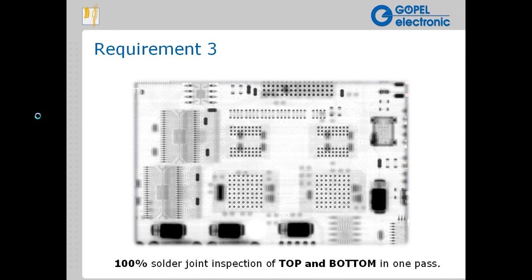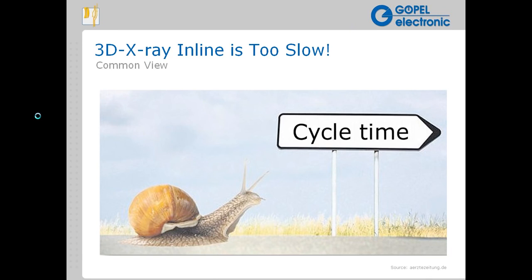To give you an example of why we are fast with X-ray, conventional AXI systems typically use a stop-and-go stepping methodology. Anytime you use a stop-and-go stepping technique like this, you have settling times that are required between images to allow mechanical aspects of the system to settle. Once you move those mechanical aspects and stop them, there's a certain amount of settling time required before you can actually take an image. So the stepping methodology is actually quite slow. We use a methodology where we do a smooth scan. So we don't stop and start for each image, and as a result, the overall scanning of the board takes place much quicker, and it's much smoother and faster, and at least is one aspect of what gives us much shorter cycle times.